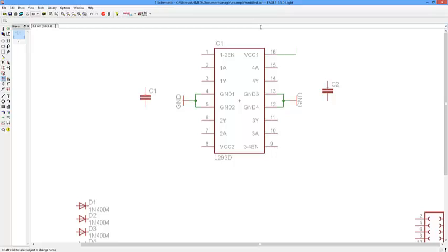Now the wire is named 3.3 VCC, but you want to see the actual name appearing. So how do you do that? You go here, label, and then select this form of label, and then go to the wire you want to label, and voila, here you go. Left click again, label is placed. So this now has become 3.3 VCC.